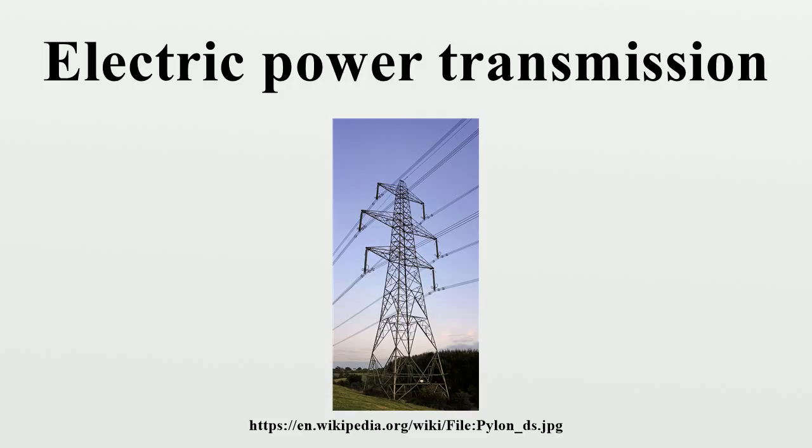Underground lines are strictly limited by their thermal capacity, which permits less overload or re-rating than overhead lines. Long underground AC cables have significant capacitance, which may reduce their ability to provide useful power to loads beyond 50 miles. Long underground DC cables have no such issue and can run for thousands of miles.